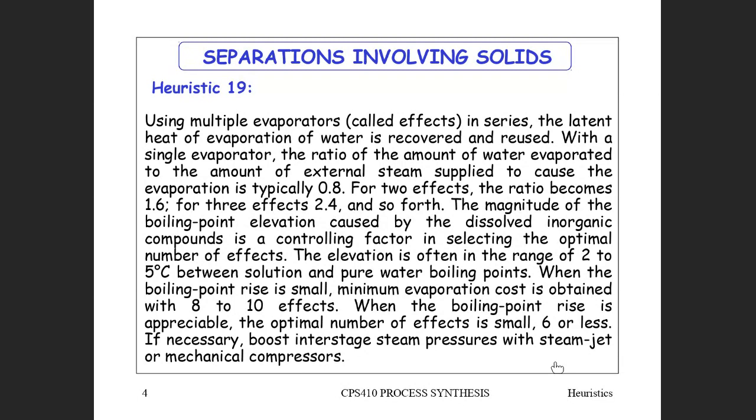The other heuristic that we used was heuristic number 10, where we said when you've got a mixture, you cool it down to 40 degrees C, and then you can apply vapor separation on the vapor side, and on the liquid stream you can apply liquid separation, which is usually normal distillation. So still no comments. I guess you're all pretty comfortable with these heuristics we've gone through today.